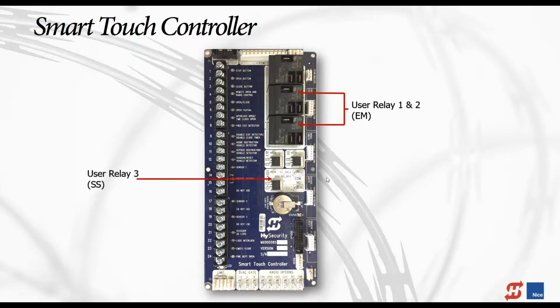And another powerful thing of our board, we have onboard relays. We have 2 of them here, 2 of the electromechanical relays, relay 1 and 2, and then we have a 3rd relay, a user relay, a solid state relay. So that allows us to do things like, on this event, we can do that, right? So maybe I want a light to turn on, or an audible alarm, or send an alert forward. That's what we can use those relays for.